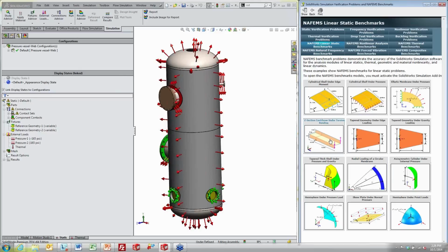I'm going to go back and see if I have any other questions, because that's the major stuff I wanted to talk about. Those three major common errors in SOLIDWORKS: dealing with the mesh with all those failures, using soft springs to help you balance out instability. And the third one is human error, human inaccuracies, knowing which solver to use, and knowing how to use your boundary conditions.